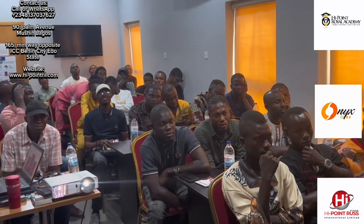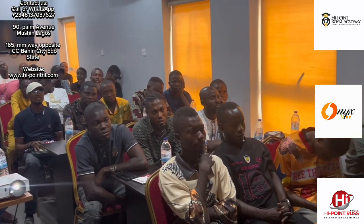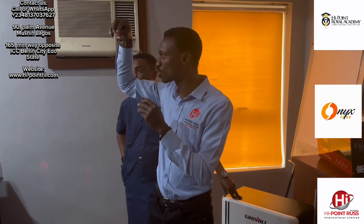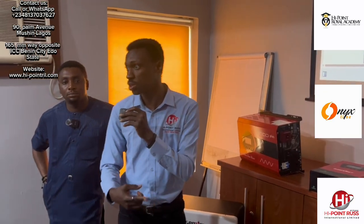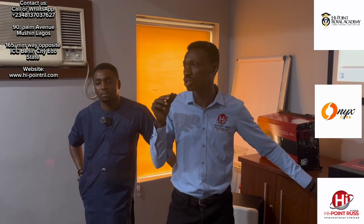When it comes to the DC load port, you are talking about it will only power direct DC appliances. You know these little light bulbs that come with all these small solar kits that people sell. Those small DC bulbs. If you have DC fans like rechargeable fans, they can work from this port. Yes, they can work from such ports, for as long as, please take note, the voltage of that device you are plugging into that DC port is compatible with the battery voltage.